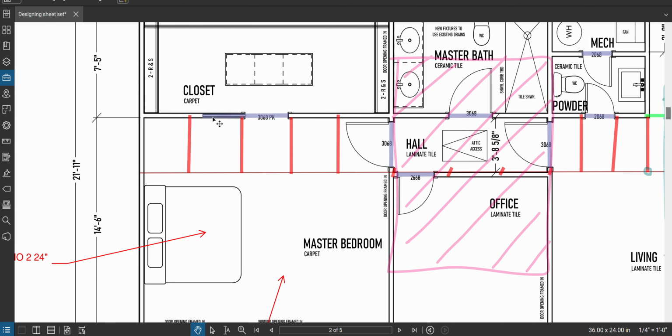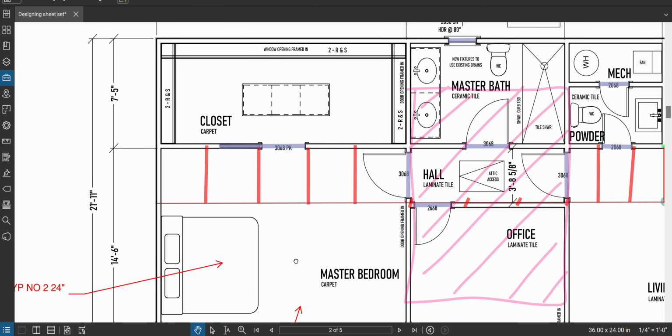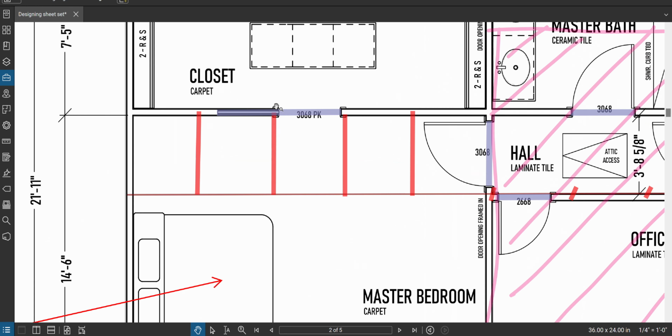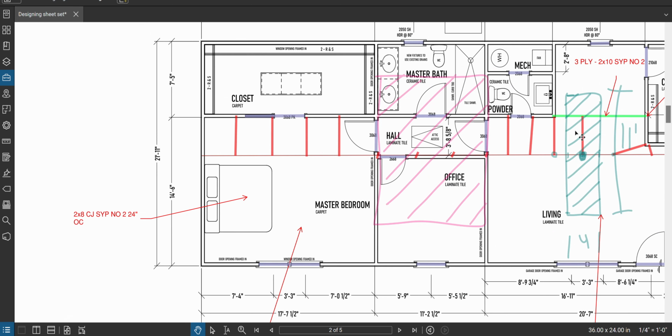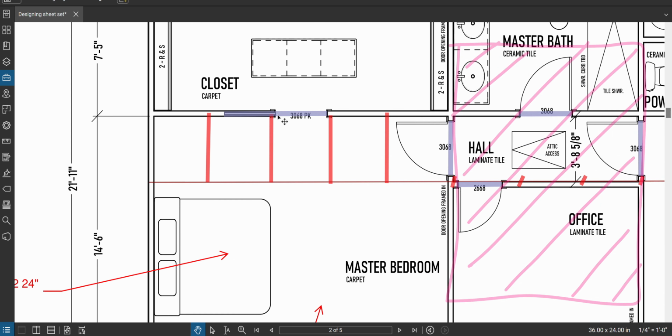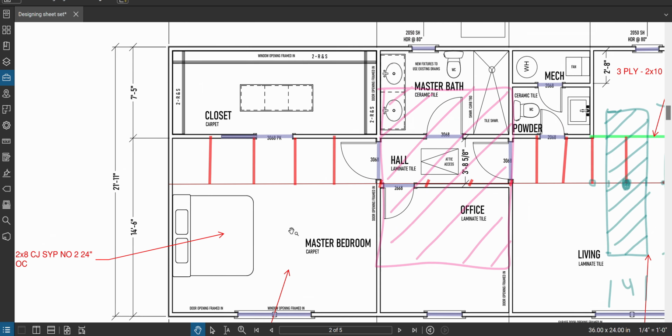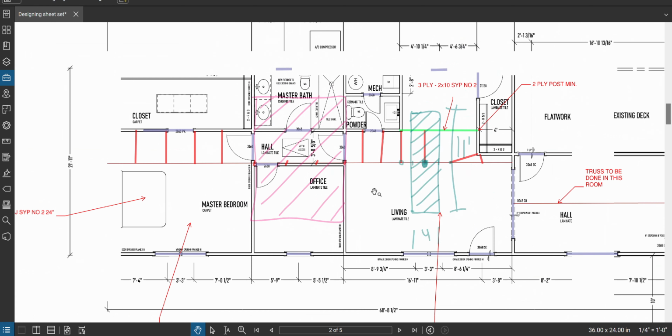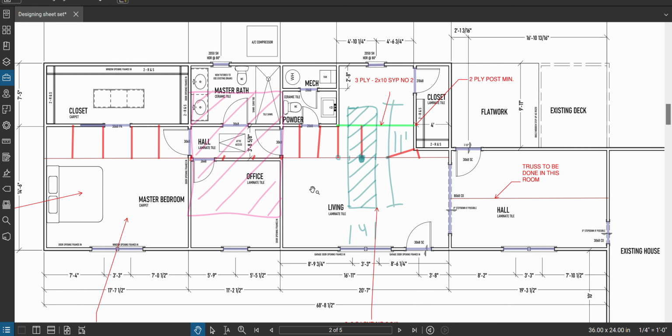And then this guy over here is holding a roof brace and a bunch of ceiling, and it's kind of wide. So this could easily be a double 2x10 header. So we're going to check all those things. In this case, you could design this if you wanted, because that's a very specific weight coming down. We know that weight would be the same as the one we did over here. So we would just copy the work we did and put it on the center of this header if we were designing it in Forte. But we'd label all our headers with their sizes. Just reference the IRC for tables or design them in Forte.